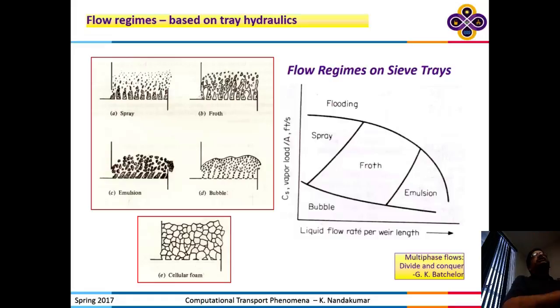They change. They change if you change the physical property. They change if you change the diameter of the column. And that's one of the challenges in multi-phase flow. The changes in the flow pattern can occur, and they are very sensitively dependent on the geometrical dimensions, the fluid properties, etc. I have a few examples of other results that will show this.